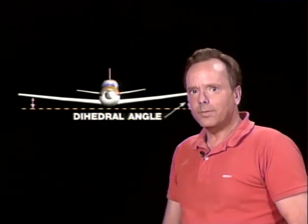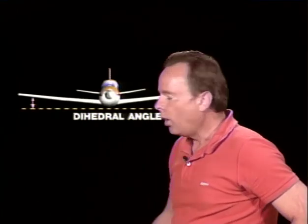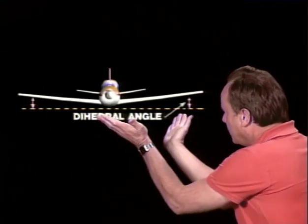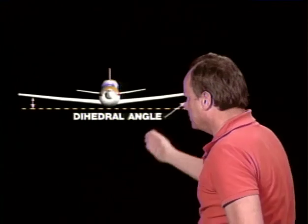They're going to ask you on the test, how do you measure the dihedral angle of a wing? One way is to place a straight edge and level protractor on the front spar of the wing, and you can measure the dihedral angle of the wing. Another way is to use a dihedral board and bubble level along the front spar of each wing. So those are two ways to measure the dihedral angle.